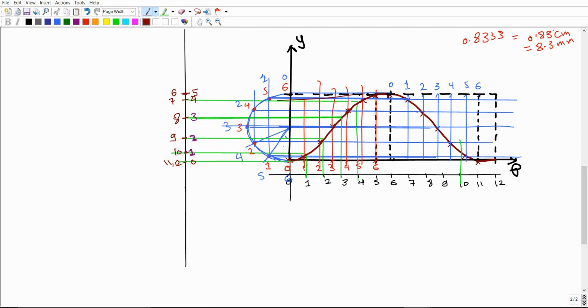Then what? Your objective, the next step, is from this 0 point, you're going to measure the R prime. What is the R prime? This is the radius of the prime circle, which is already given to us at the top as 20 millimeters. So R prime was given to us as 20 millimeters. And your objective also is to calculate the R base, the radius of the base circle. We said that the radius of the base circle should be R minimum, the minimum radius of the cam. But he didn't give us a minimum radius of the cam.